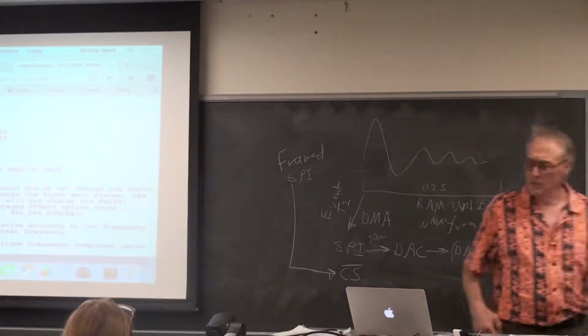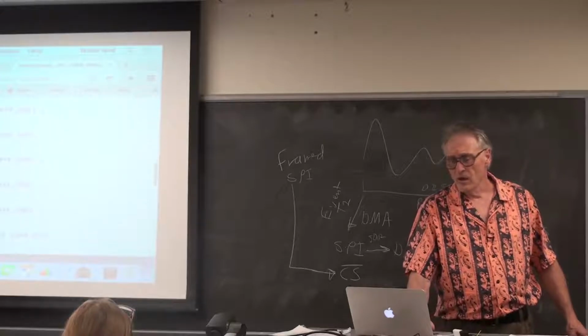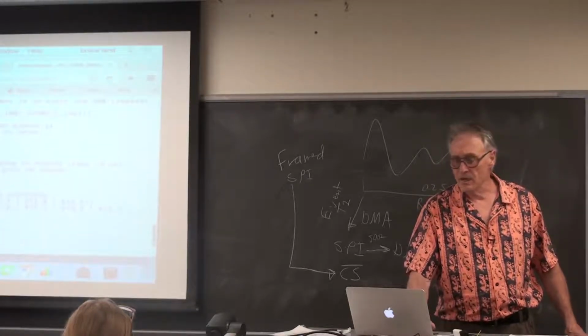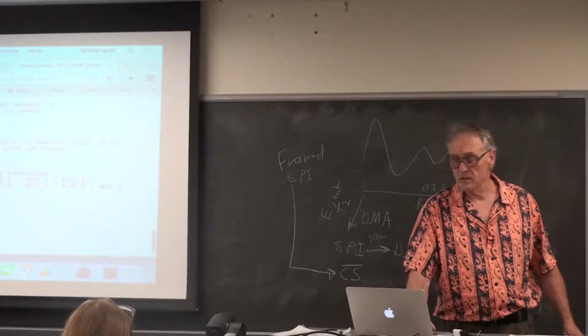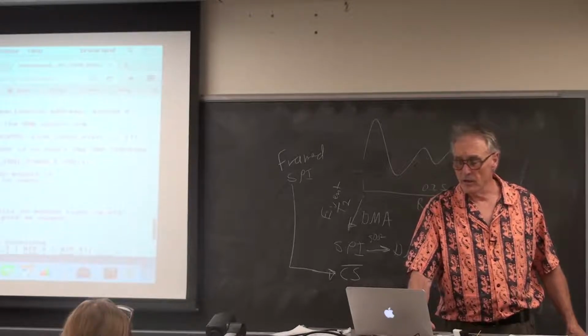You do not need to do this. You do not want to do this. And I was synthesizing sine waves without using direct digital synthesis, so I had to bend over backwards to get the scaling correct. But the critical part here is setting up the DMA transfer.